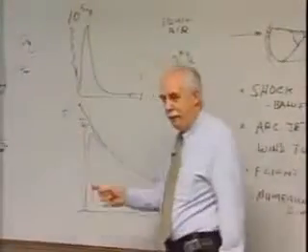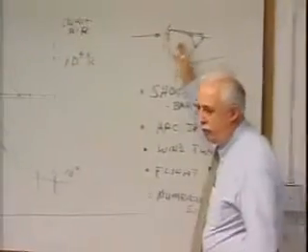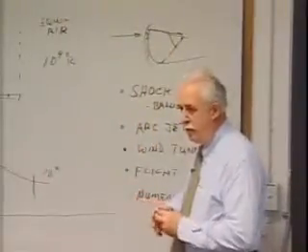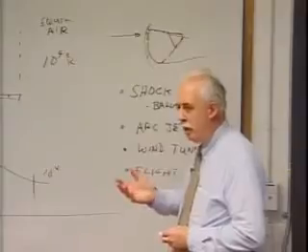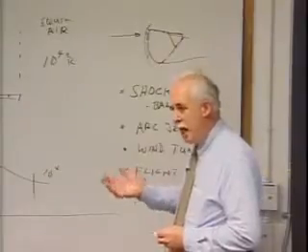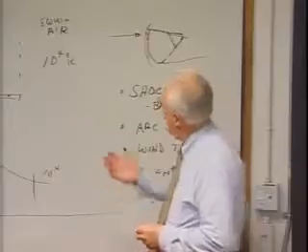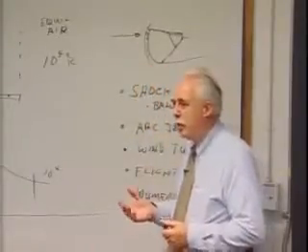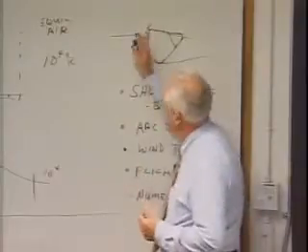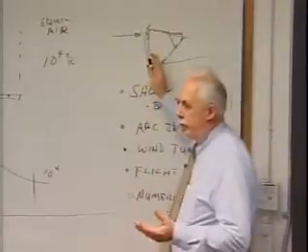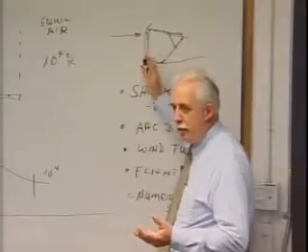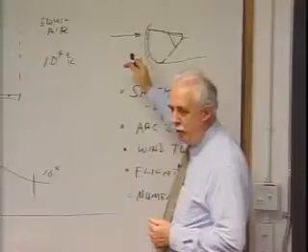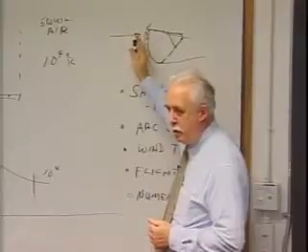This was our flow field interest on Apollo primarily because of this radiation. Okay, we had to understand the flow field in order to be able to compute the radiation. About half of that radiation is optically thick from the ultraviolet deionization radiation and also line radiation from atoms. The other half of the radiation is basically optically thin, the molecular band radiation and other things. So we needed to understand the flow field. All right, we did some pretty crude engineering calculations in order to get that flow field, but we were focused on getting to a numerical simulation of the subsonic region in particular.